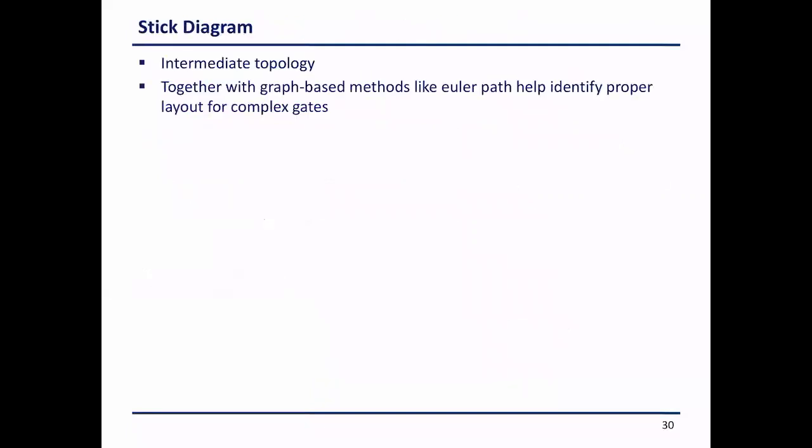Now we're going to talk about the stick diagram, and the stick diagram is important for us because we're going to deal with the logic gates again using those stick diagrams. And we're going to revisit the NAND, the complex CMOS gate, using the stick diagram. What does the stick diagram tell me? It tells me, before you start to print the layout on the simulator and the tools, I want to know a sketch of how you want to lay it out.